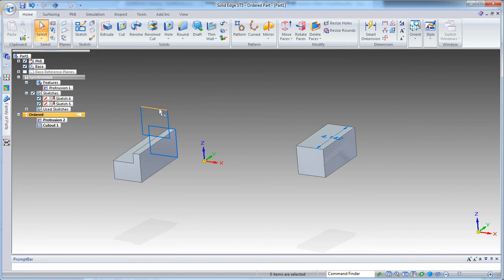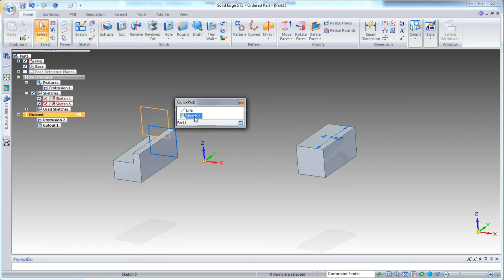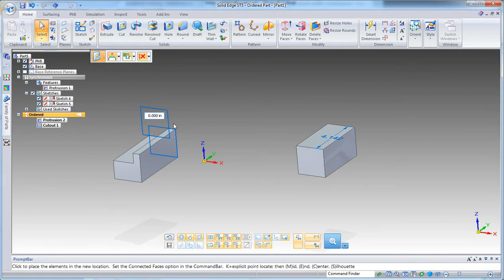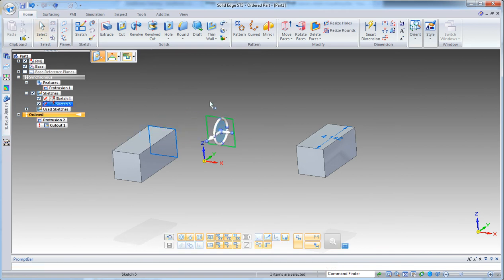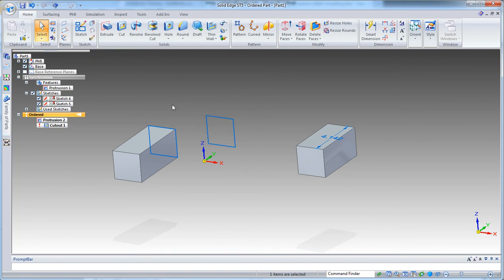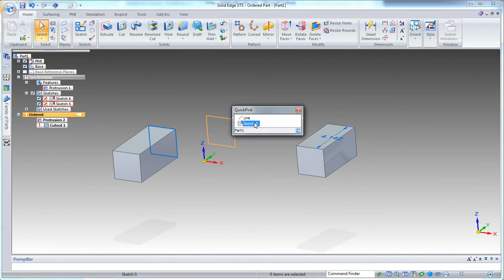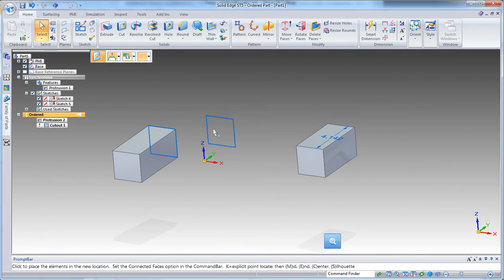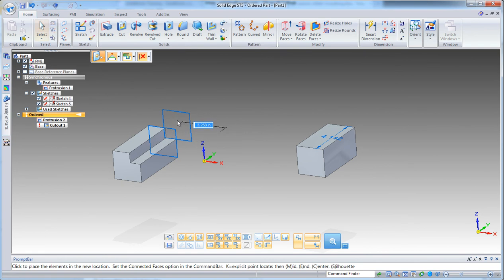So if I select my synchronous sketch, I can move that sketch and cut whatever I need. If I move outside of any body, I will simply have a failed feature, so that's no problem. I can go to my sketch, move it back so it cuts something,